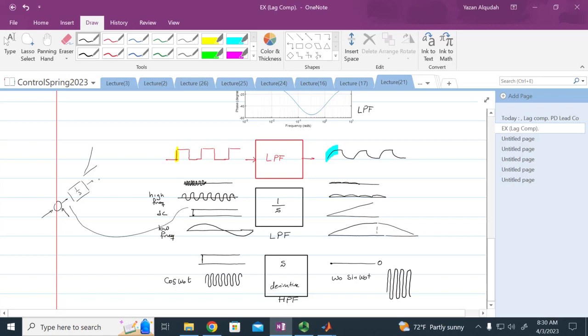And therefore, if this is a motor that I'm trying to move to a certain position, that error signal is getting bigger and bigger, and therefore is going to drive the motor to move to reduce that error. Does that make sense? The same thing happens with all these low-pass filters. A very small signal gets amplified by the integrator. This error signal by itself is not enough, for instance, to drive the motor. But with time, this signal is going to get bigger, enough to drive the motor to the right place to reduce that error.